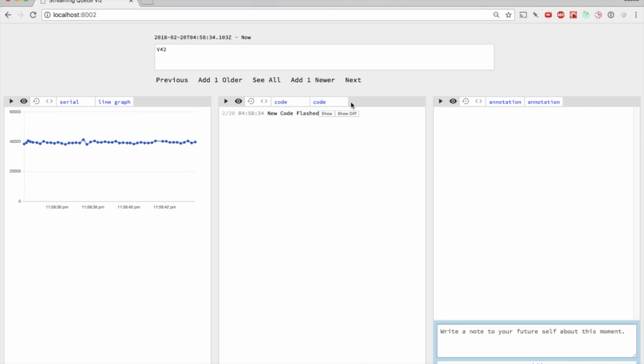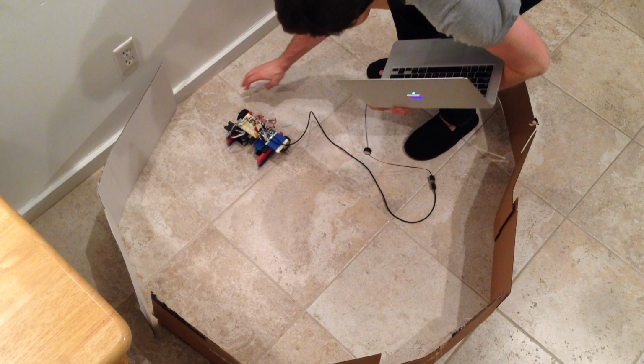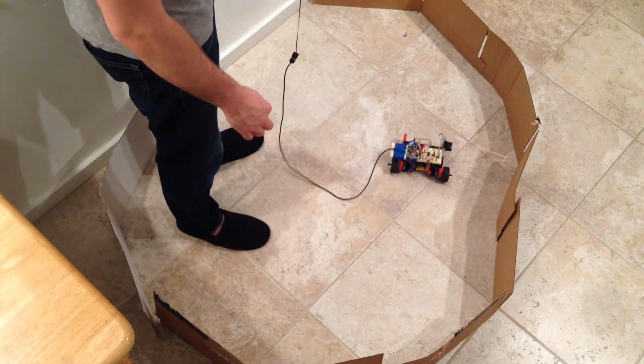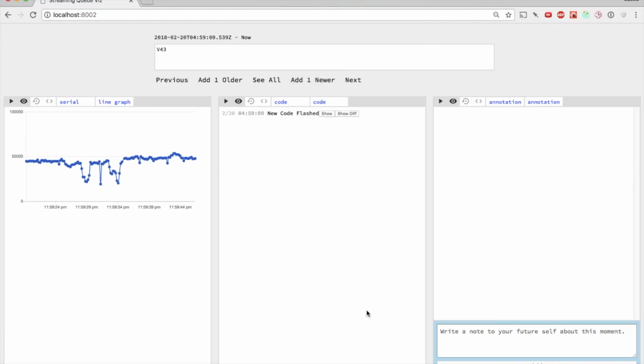Next, I try using proportional control that turns a different amount depending on the error. Initially, it turns too quickly, so I decrease the effect of the error. The robot drives smoother, and I see there are fewer oscillations than before.